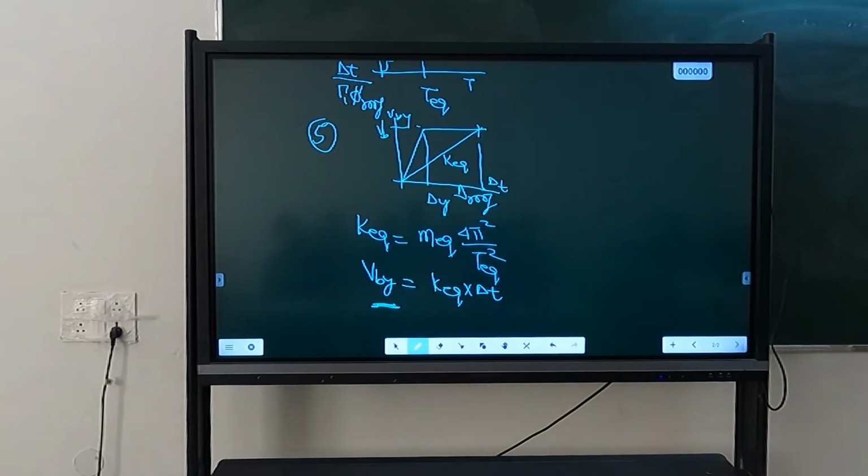Yes, we are assuming here also there are certain assumptions. We are assuming that there is not much change in the mode shape of the preliminary building and the building which you will be designing. There won't be much change. There can be change in the period, but in the mode shape, the change will be less. That is one assumption.